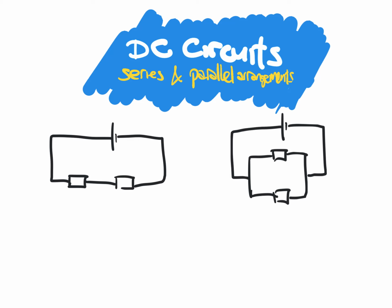In the chapter of DC circuits, generally what you are asked to do is to use this formula, V equals IR, and how are you going to apply it into these two arrangements, series and parallel? In each of these arrangements, you're going to have three rules each. And the three rules are going to be about what the current is like, how do you look at total resistance, and how do the potential differences add up or split up in that arrangement, right?